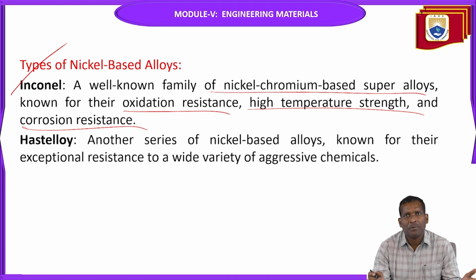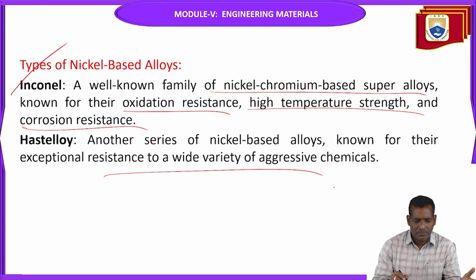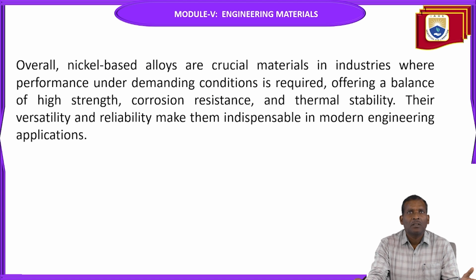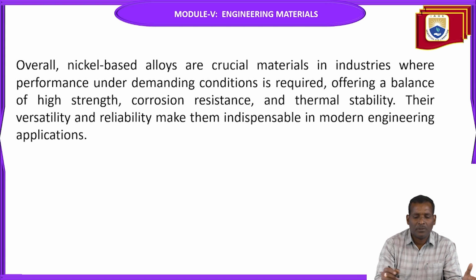Another series of nickel based alloys is known for their resistance to a wide variety of aggressive chemicals. The category is called Hastelloy. The overall summary: these nickel based alloys are crucial materials in industries where performance under demanding conditions is required, offering a balance of high strength, corrosion resistance, and thermal stability.